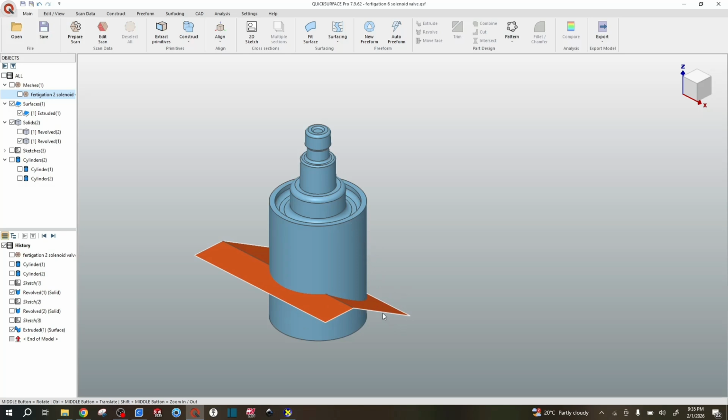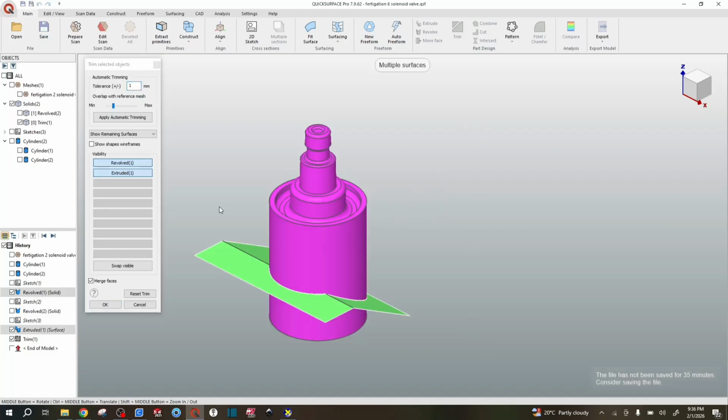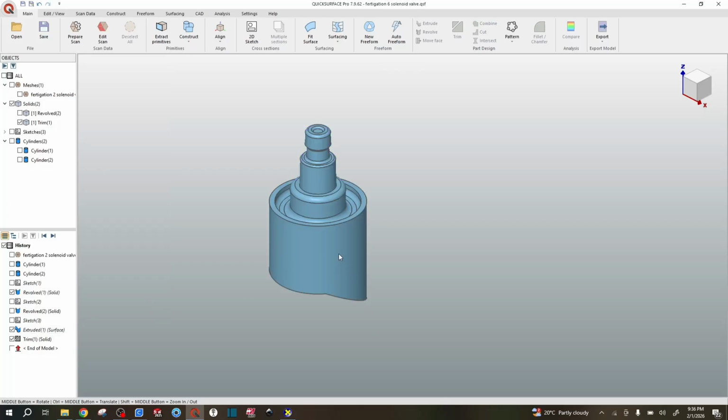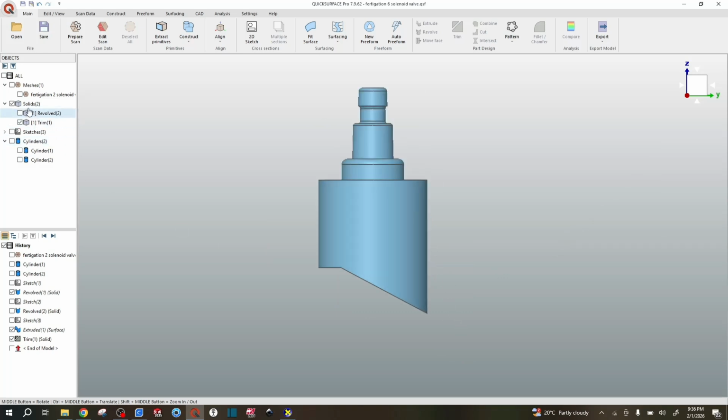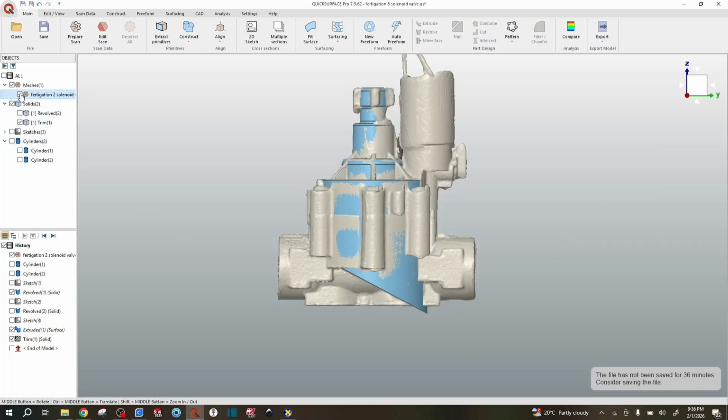And now we're going to use this surface that we've just created to slice this body. So you can highlight everything, and then it's going to give you an option for trim. And then you can see the two bodies are selected, and then we just left click, just like that, and you can see it's okay. And that's what we come up with.